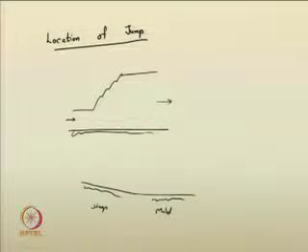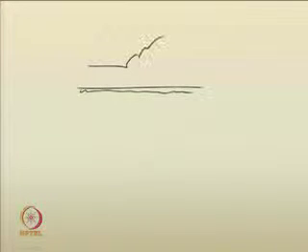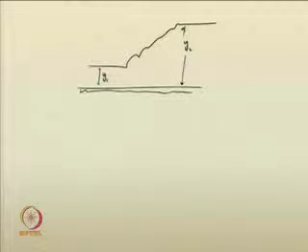So, there is a probability of occurrence of hydraulic jump. We do not know at which location the hydraulic jump may occur. When we studied the hydraulic jump, you have already seen that it consists of a pre-jump depth and a post-jump depth. We have seen this thing. The specific force at the pre-jump location and the post-jump location are the same.